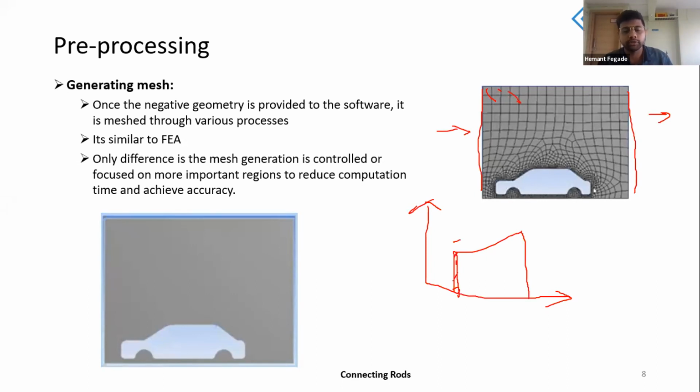Usually, if I give you an example, if there are 20 lakh cells involved in a simulation, or let's consider a bit more, 40 lakh cells in a single simulation, and you have a PC that has 64 cores, consider this as a different level of computational source, because usually we have 4 or 5 cores in laptop or computer processors.